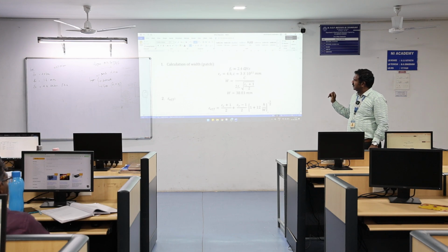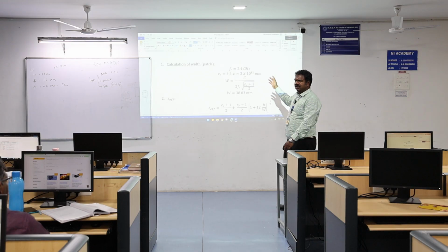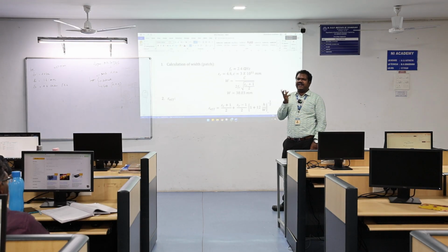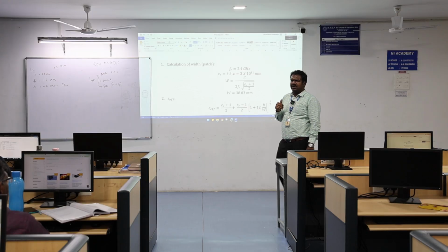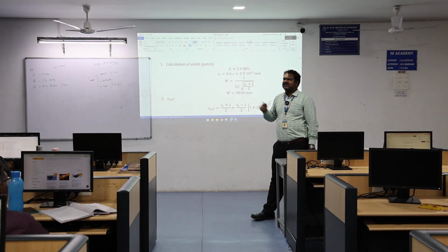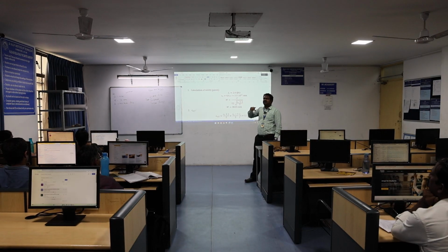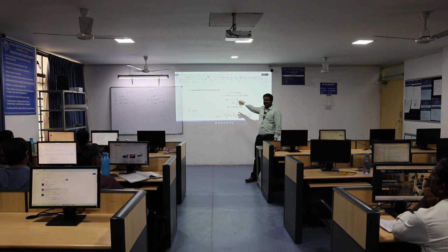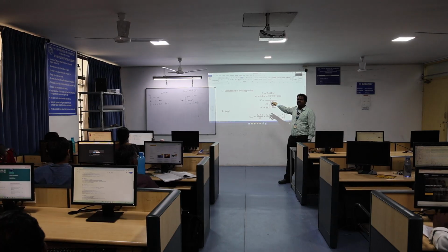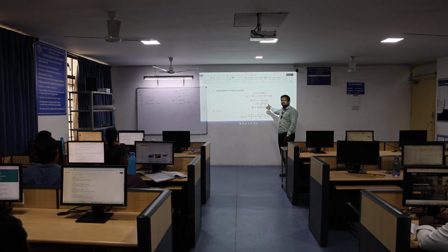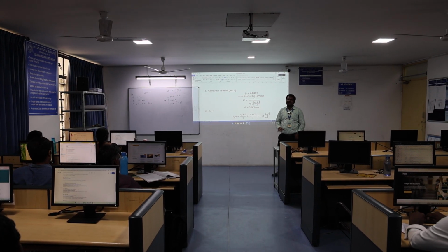It is not a fixed value, sir. We choose our own specification: what is the minimum range, what is the maximum range, based on the frequency and specification. For example, if you want to design for a 4 GHz antenna, while the dielectric constant here is 4.4, these values vary by using the calculation.